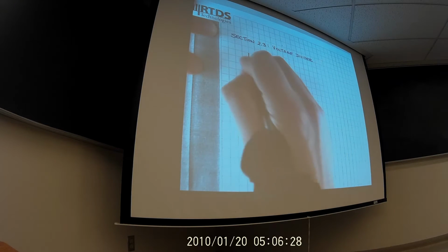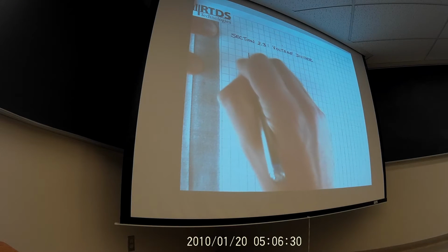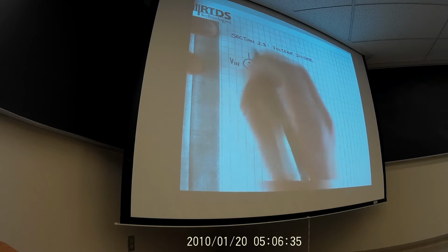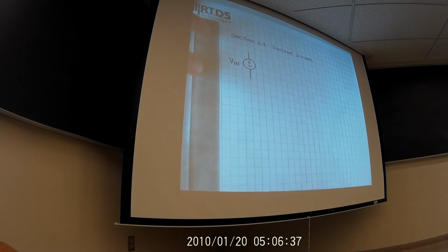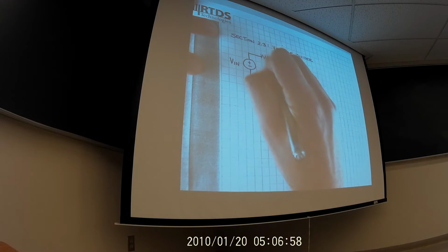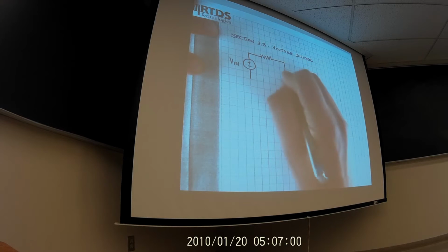So it's a pretty basic circuit, but it's a handy one. What we have is a voltage coming in, which we're going to call V in. And let's say we have a DC source coming in at 12 volts, and you have a component that operates at 5 volts DC. Now there are many better ways to attenuate that voltage than this, but this is the first one we're going to talk about. So a voltage divider is just 2 resistors in series.